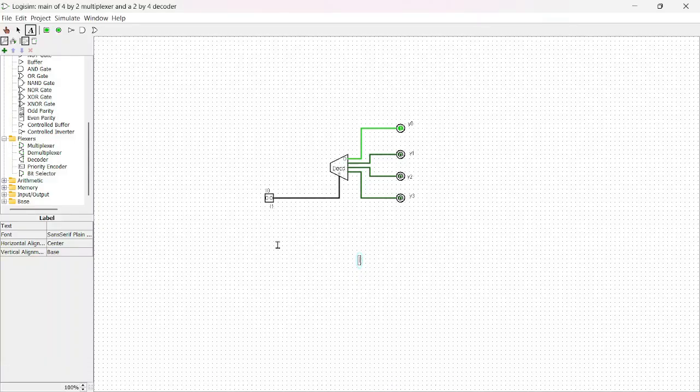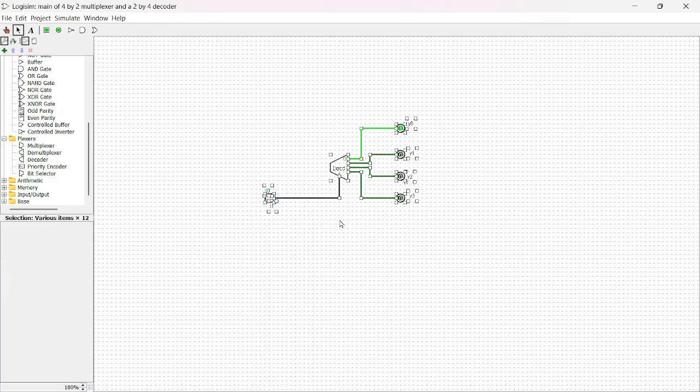This is a sample decoder I just drafted. As you can see, if I1 is 0 and I0 is 0, I have Y0 to be on. If I have 0 and 1, I have Y1 to be on. If I have 1 and 0, I have Y2. If I have 1 1, I have Y3 to be on. So these are my outputs and this is my input.